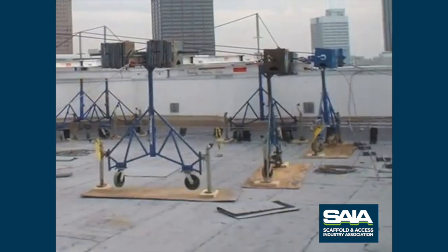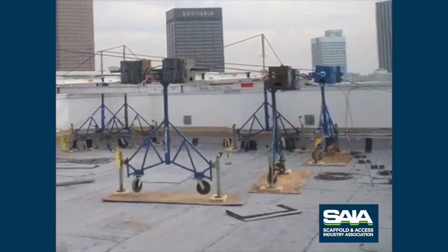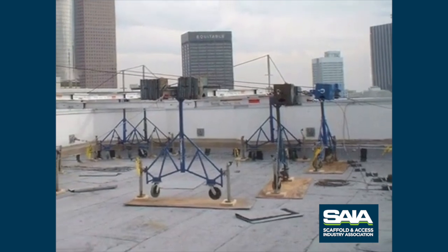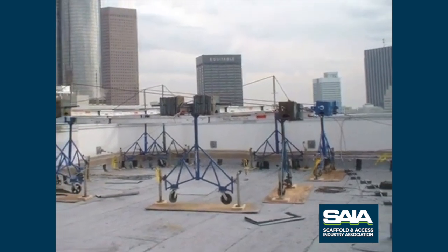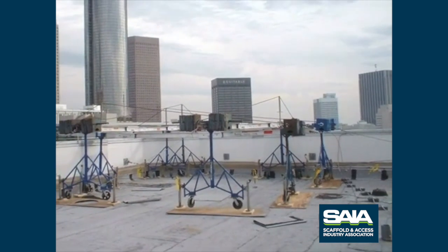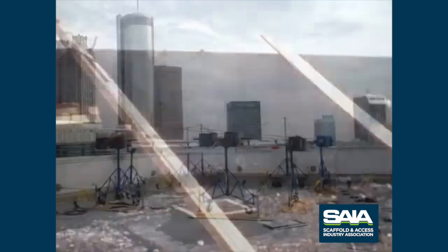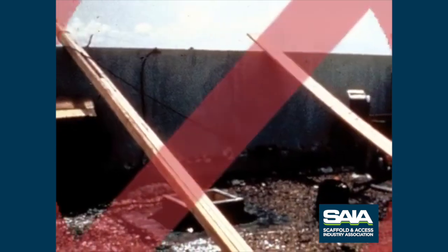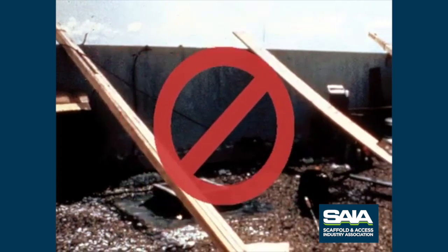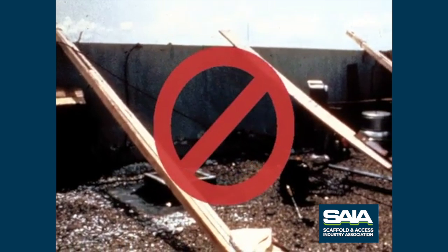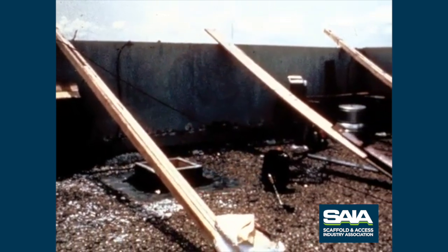Protect the roof and distribute the load at the bearing points using plywood or planks. A qualified person must be able to determine that the roof can carry the load of the rigging. Do not use outrigger beams made of wood. Do not use flowable materials such as sand or water for counterweight materials.